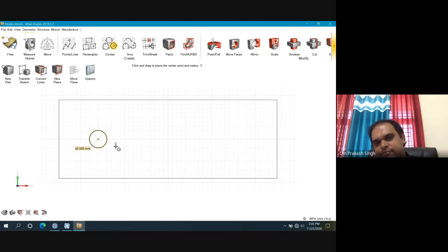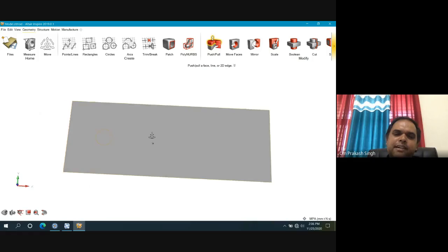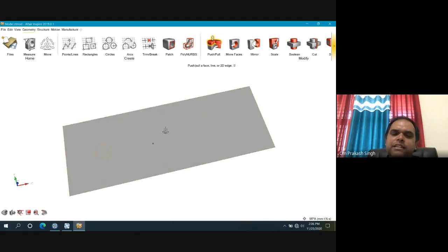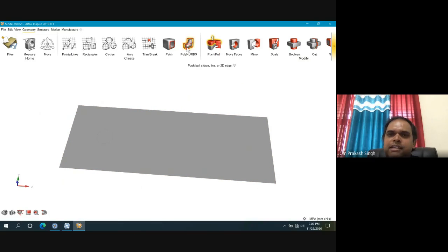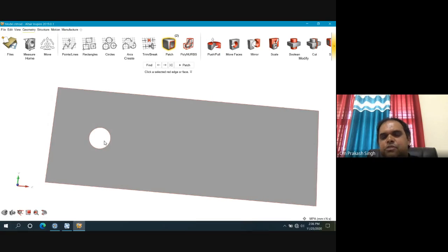Flow over the cylinder. I'm not bothered about what is happening inside the cylinder. So my geometry will look like this. Ideally, it is like this, so everywhere there is surface. So what I'll do is this subtract Boolean, in a sense, you just subtract this. You remove this surface. Now I have removed this surface. Basically, here it is hollow, meaning if there is no surface, it will act as a solid. So the flow will come over this solid and it will deflect.